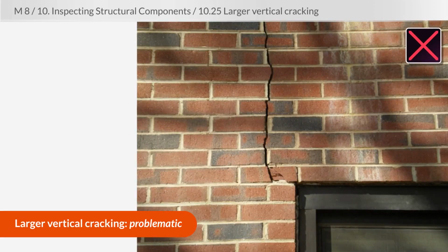And while this is a vertical crack, it's pretty big. And it's coming off the corner of a window. Possibly that's due to some lintel problem or some other issue. But definitely recommend further evaluation.